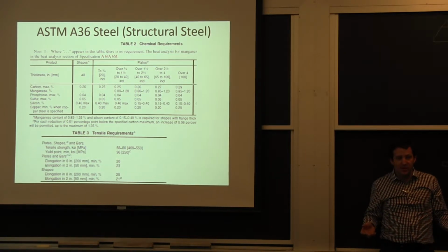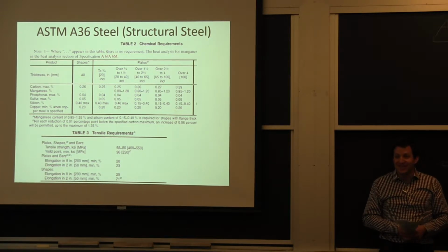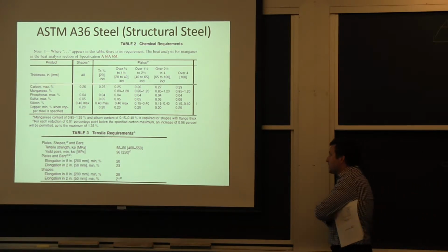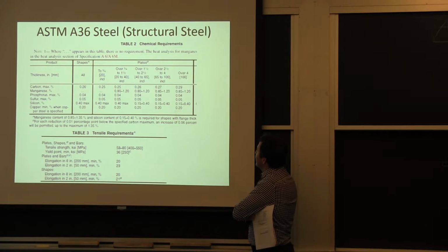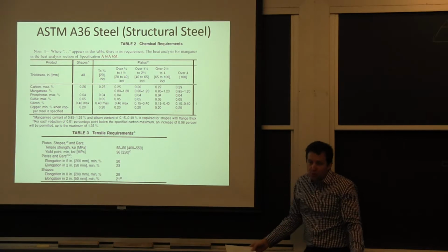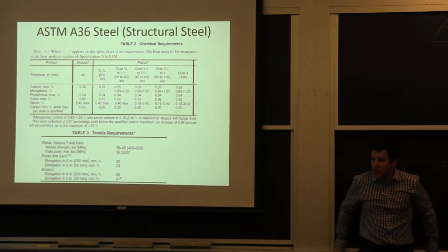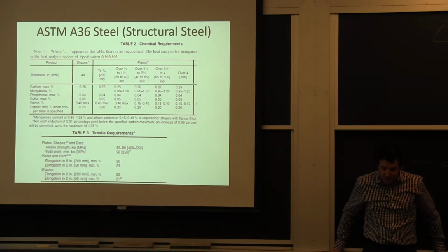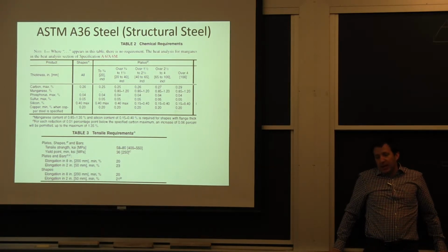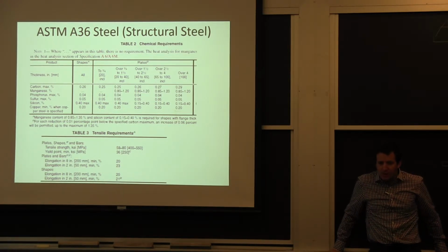If it's a structure that's being used, taking a coupon out for testing, you have to explain yourself a lot. So a lot of times, what ended up happening is I was building a case that because the chemistry was right, and it was at an age where the control for manufacturing steel was fairly consistent, that we could just assume that it was the most basic structural steel and weld it accordingly, according to regular welding procedure. And as a safety precaution, we always had more non-destructive testing after the fact.